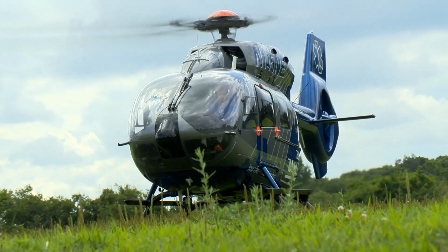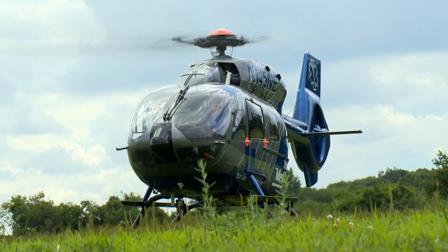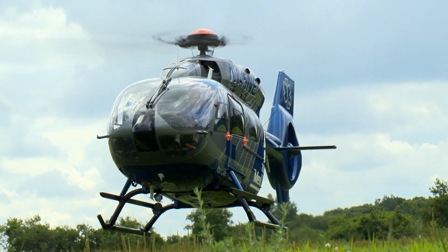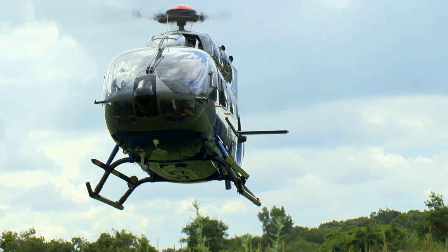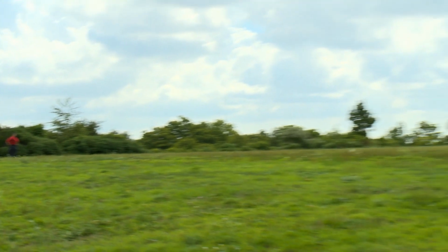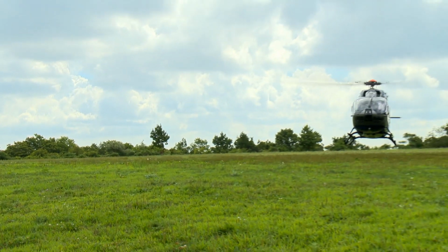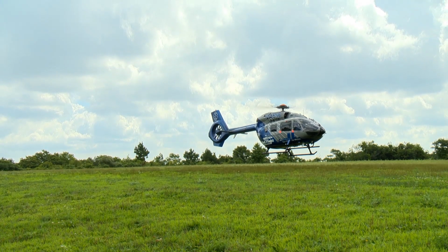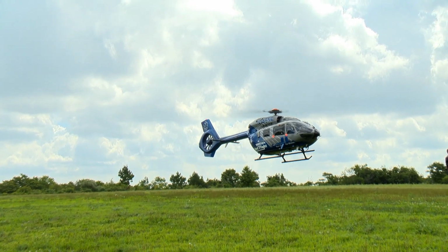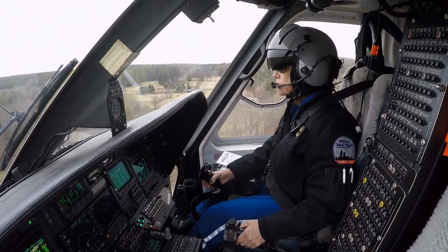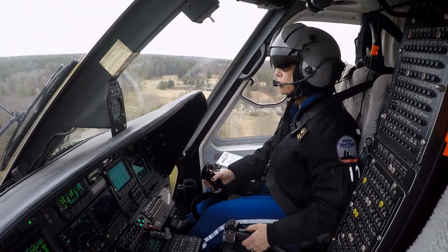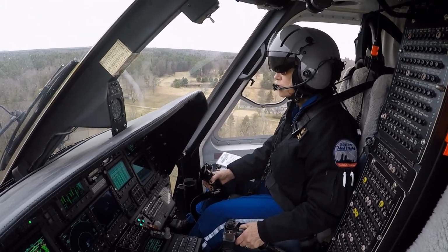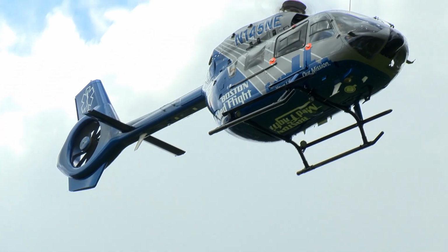The pilot will typically lift the helicopter into a hover a few feet above the ground to check that all systems are functioning properly. If the LZ is a confined space, the pilot will then turn the helicopter into the wind and lift straight up or slightly backwards until it is above all obstacles in the area. Finally, the pilot will transition to forward flight by lowering the nose of the helicopter and accelerating away from the LZ. This procedure can take a few minutes. However, this is normal and should not cause any alarm.